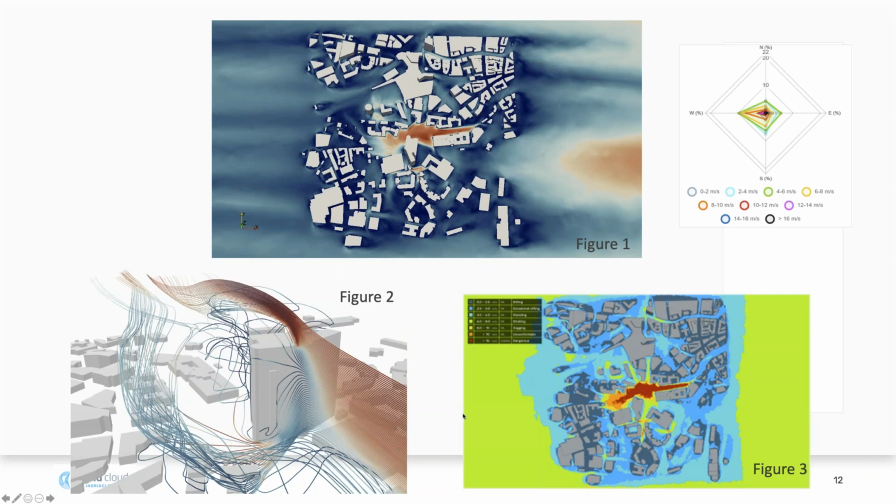And then you can also do a full pedestrian comfort analysis as shown in figure 3. With full, I mean, you not only consider the wind from the west, but you also include contribution from the wind from the south, the north, from the other wind directions. You summarize all of them together, and then you get kind of a heat map. I will explain the colors later on in the presentation, but just to show, if you would have done a full pedestrian evaluation, this area would have been marked as unsafe. So you could have predicted it already.